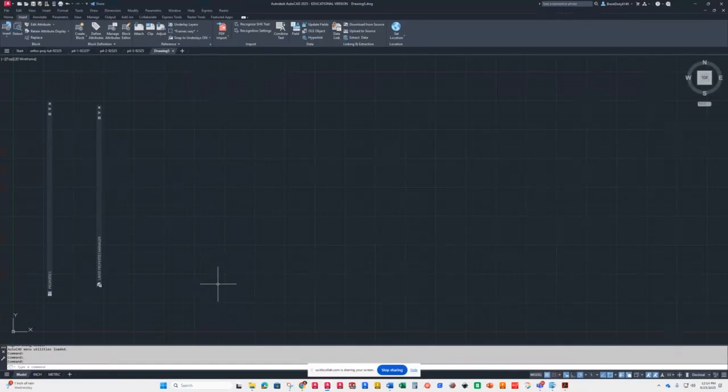Now, if you'll notice, it doesn't give you a width for the top of the tunnel roof. Okay? Well, that top of the tunnel is the same width as the top of this cut-off pyramid. That's the way I draw it. The bottom is 1.5 and the top would be 1 inch. Now that's going to cause some overlapping lines, and this is where line precedence comes into play.